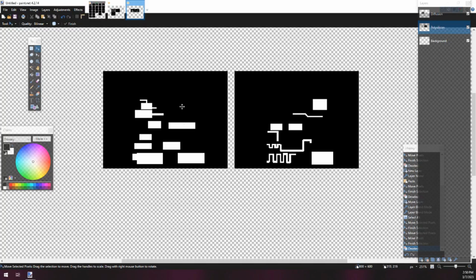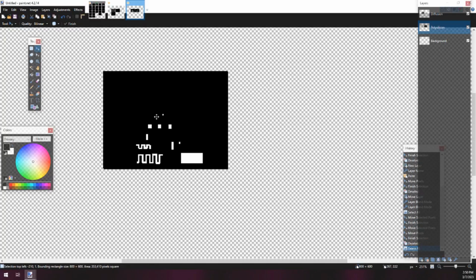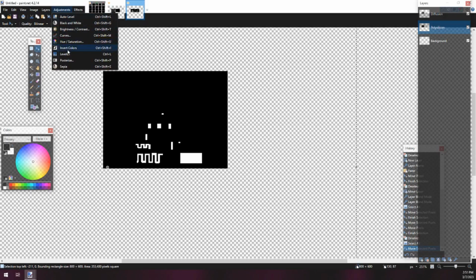In this case, I have the diffusion mask and the polysilicon mask. We can do that simply by ANDing them together. So if I AND the two together, what we're basically left with is any overlap, any parts of the diffusion circuit that is overlapped by the polysilicon. And so during the first pass, what we can do is turn all of these into separate wire masks, and what that will result with is basically wire masks that are just the overlap. What we can then do is invert the polysilicon mask.